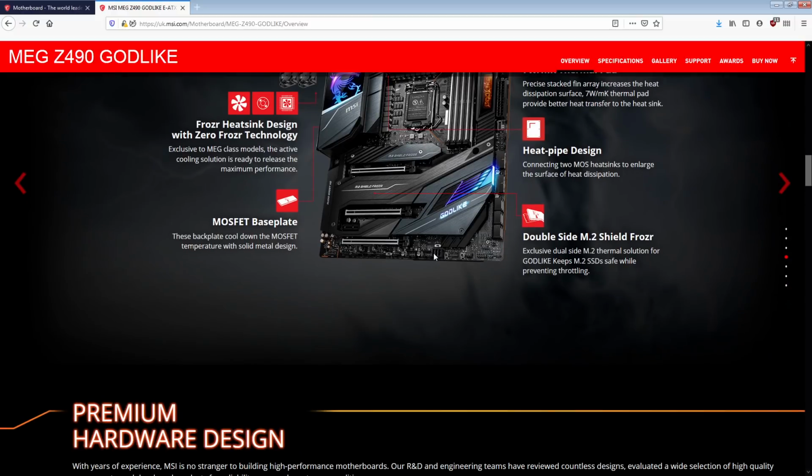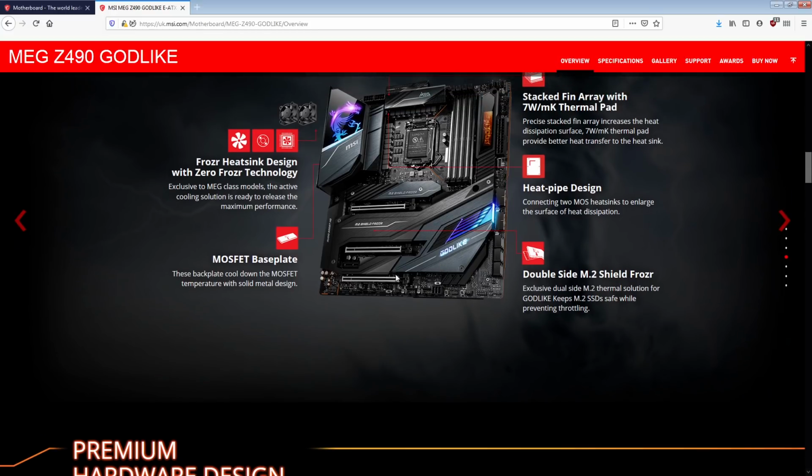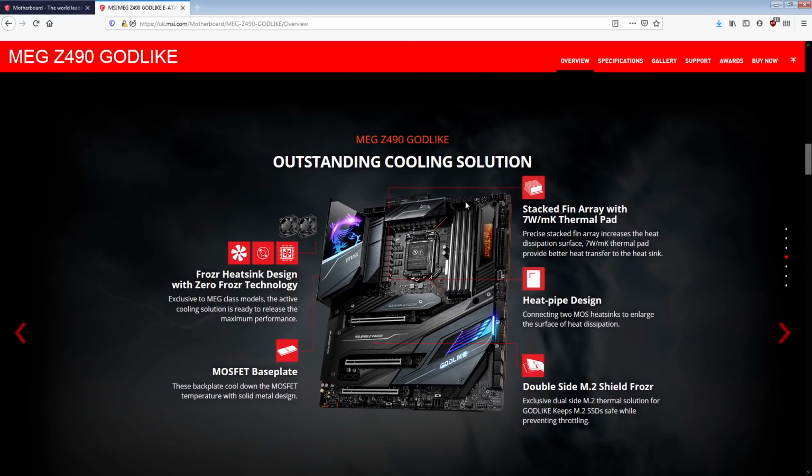Other dumb things, that 6-pin power connector is physically impossible to plug in while also having 3 GPUs, making that 6-pin power connector completely bloody useless, because normally, if you're running just 2 GPUs, you won't have a problem with the power delivery capabilities of the 24-pin power connector. That's only a concern if you're running like 3 GPUs. Well, you can't fit 3 GPUs and the 6-pin at the same time, so that's really dumb.